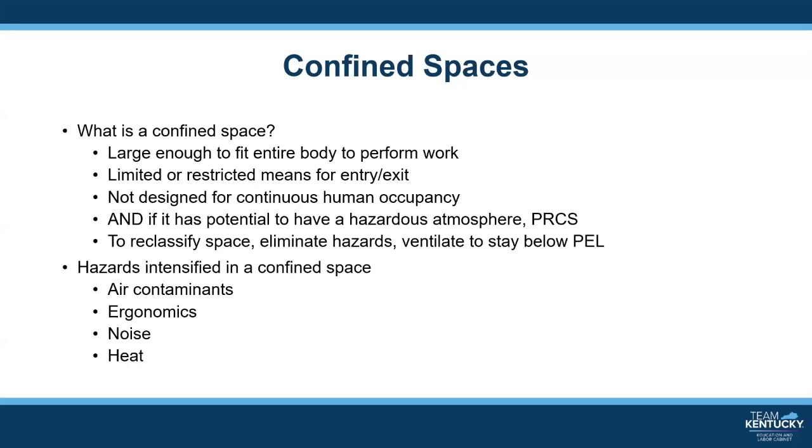Confined spaces while welding means a relatively small or restricted space, such as tanks, boilers, pressure vessels, or a small compartment. They are spaces that are normally enclosed by solid walls and have no natural ventilation and have restricted means of entry and exit. You should always stay aware of gas emissions during larger breaks.